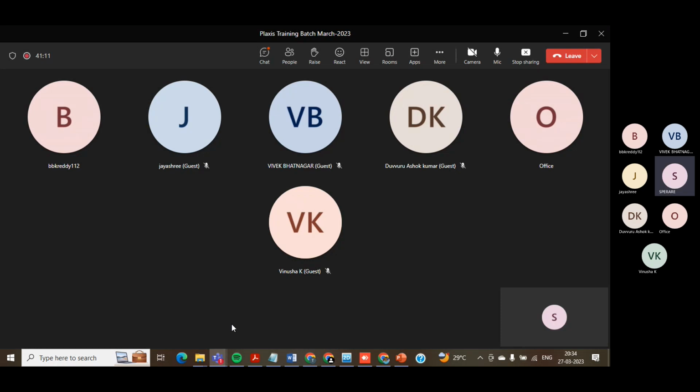Now just see this. Whatever the footing to footing spacing, there might be at least a 0.5 meter gap, right? So let's do it separately. See what happens if I do the rectangular footing separately and what happens if I do the circular footing separately, observe the results, and then merge them in an Excel sheet, and then you can check what the exact output is. But this is a method of approximation when you have a limitation. You have to do this analysis separately.